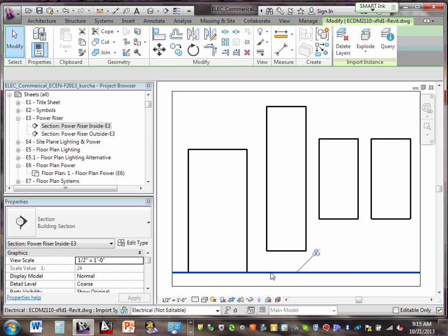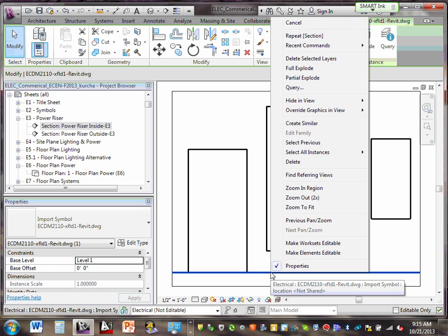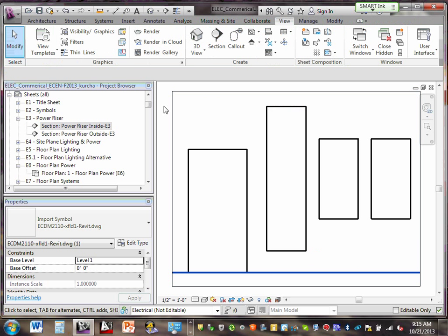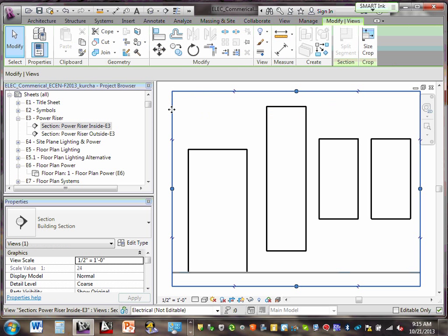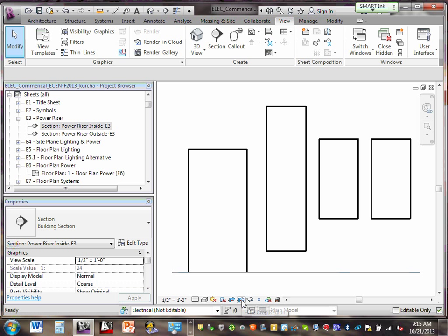Click on this stuff. Okay. And click on it. So let's start with the view. Can you guys see first of all, that view that you see? Let's go turn that view off. So remember that one here? Trim, hide, crop view. Click on hide crop view. Did you guys see how I hid it? Hide crop view. That's easy to do. Did you guys do that?